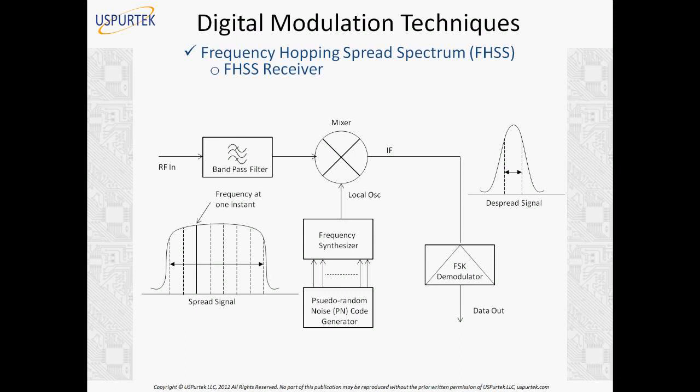So as I just said, in FHSS we cannot use QAM because of the incoherent phase from one frequency to another. Okay, so there's a question, why not QAM again, please? So, in quadrature amplitude modulation, we have to maintain a very strict phase difference between I and Q signals. We have seen that before. So phase is very important. Phase coherence has to be maintained. The phase should not change actually. We have seen what phase noise can do.